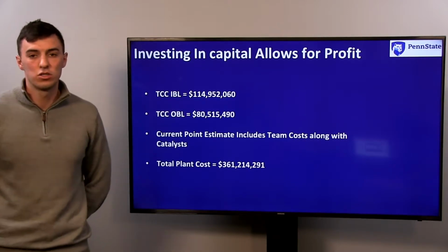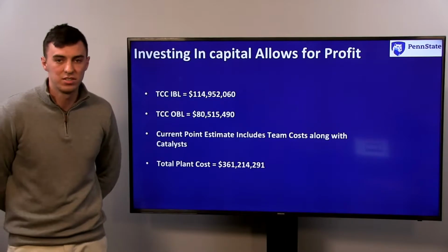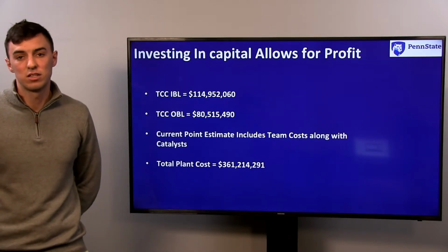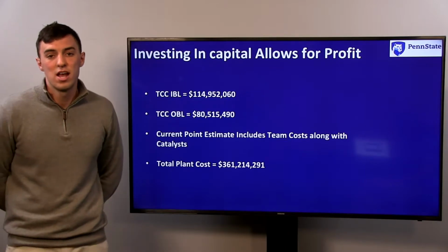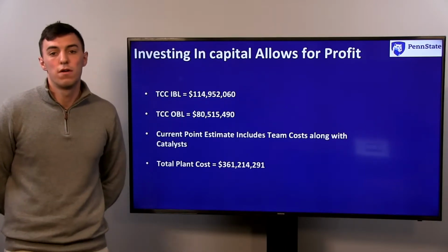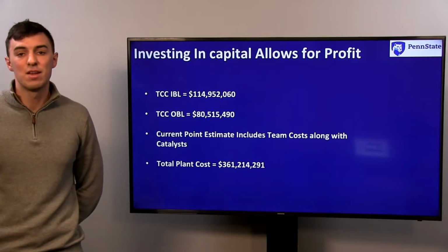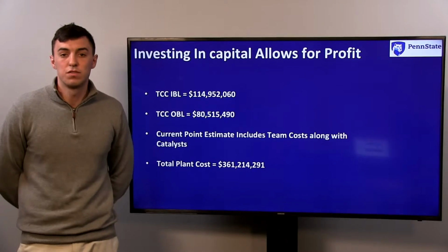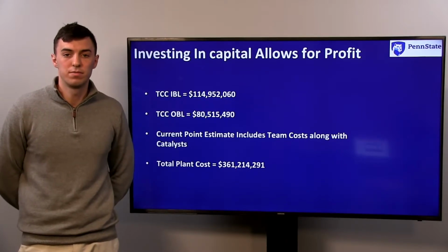Now, the one fixed cost we had, in addition to these, were the catalysts for both reactors, the monocyclohexane reactor and oxidehydrogenation reactor. Now these costs were fixed, as I mentioned, and had to be renewed every 3 years. The plant life cycle is for 15 years, so these were multiplied by 5.